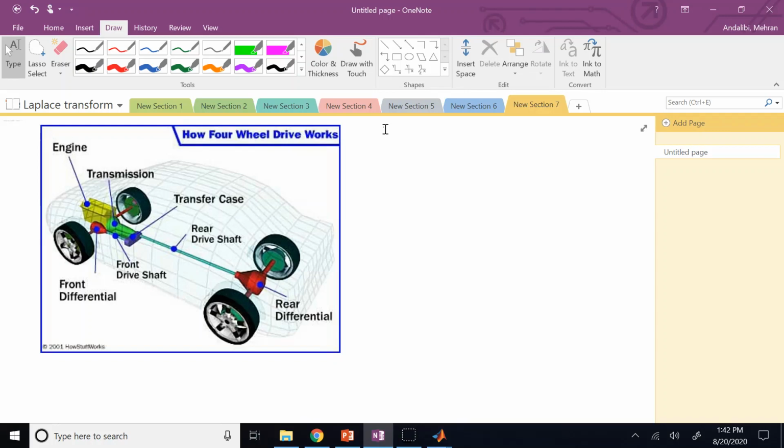It determines the acceleration, and then that push will determine the amount of fuel that goes to the engine, so that will determine how fast the engine rotates. That RPM goes to a gearbox, comes out of the gearbox different, then goes to the drive shaft, goes to the differential if it's rear drive, and then in the differential, the direction of rotation is rotated 90 degrees and goes to the tires, and then that RPM is multiplied by the radius of the tires to give you what?